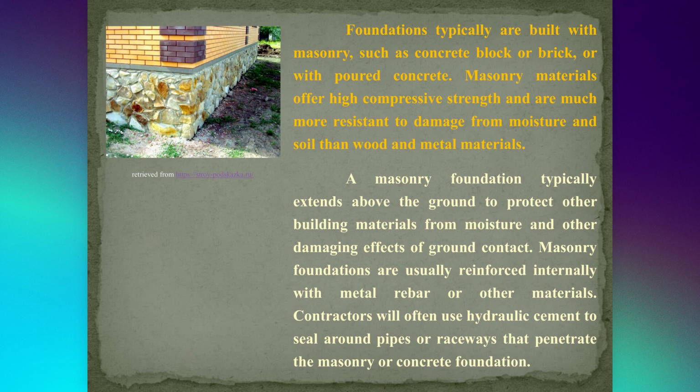Masonry foundations are usually reinforced internally with metal rebar or other materials. Contractors will often use hydraulic cement to seal around pipes or raceways that penetrate the masonry or concrete foundation.